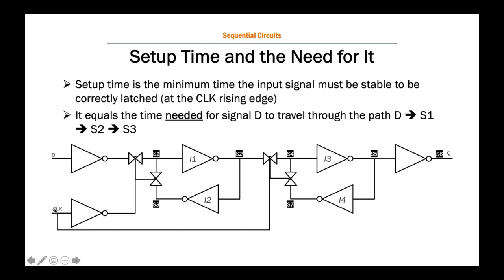So here's the clock. When the clock is still going to happen in the future, I'm ready, because that signal at T minus 3, T minus 2, T minus 1, T0, at the time the clock happens, you're properly sampling the value of D that you were looking for. Otherwise, you're risking sampling something else.